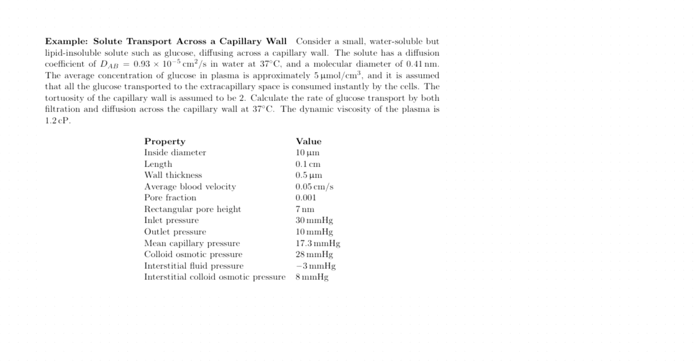Okay, so let's recall from last time. We have the equation for ṁ_A, the mass transport rate: ṁ_A = C_A(1 − σ)Q + C_m S Δ C σ.